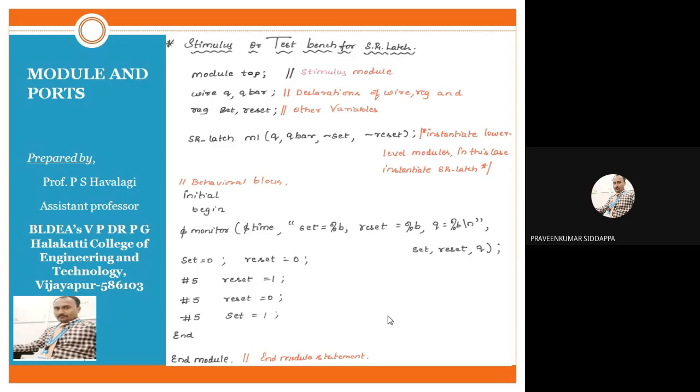Okay, so this one we have called the test bench. You have to practice it, write your own test bench. There are no difficulties in writing the test bench. The first four are compulsory. Why are we writing the first four? That should be clear. The next two are also compulsory, initial and begin. After initial begin, monitor is compulsory. Next, apply the inputs. You can apply the inputs by writing the delays or without writing the delays also, no problem. The delay is optional.